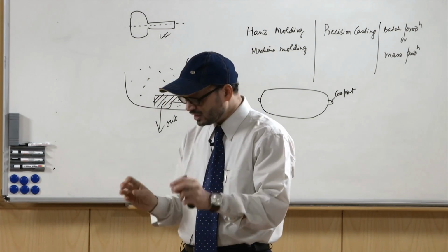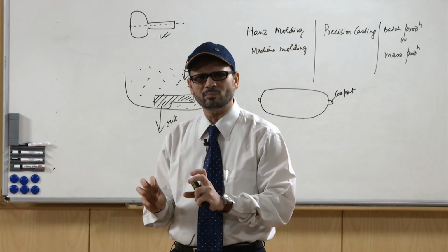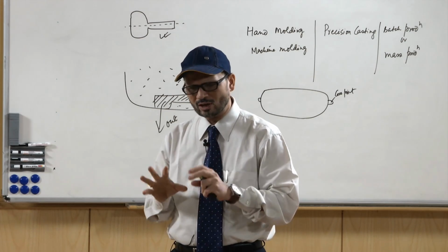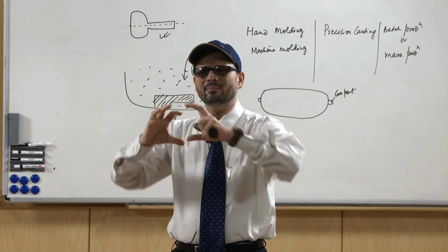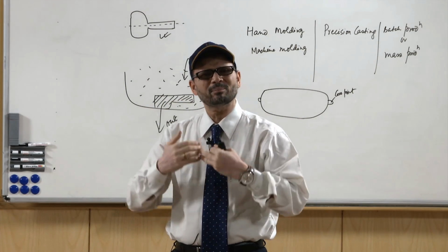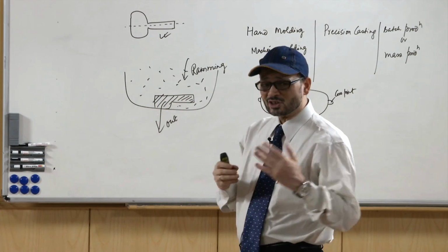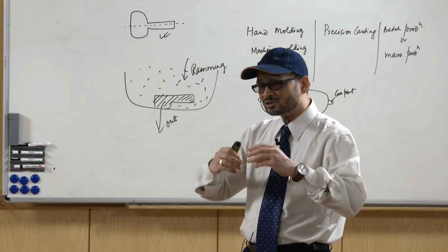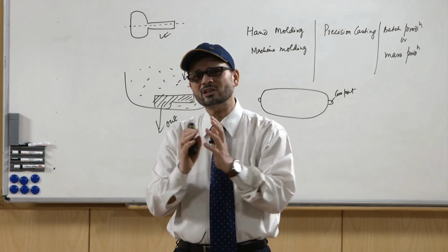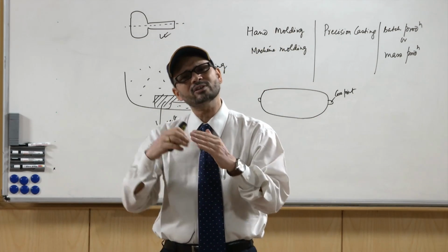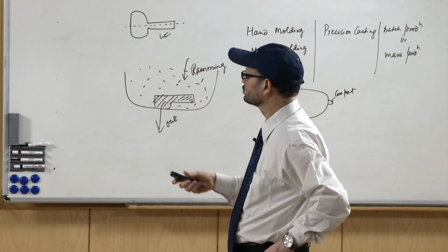So, in the cavity if you put the gypsum plaster of required amount and give the water, mix them and leave them, they will take that particular shape and your pattern is made. So, this is a good material. It has also certain expansion coefficients, it expands. So, basically it also takes care of that.